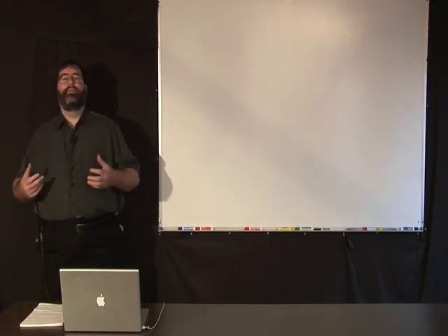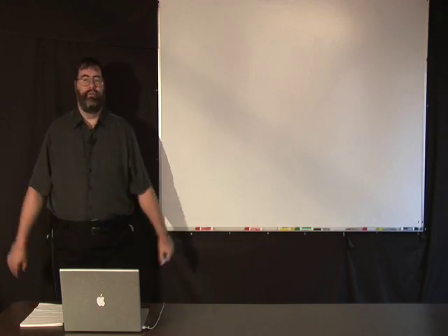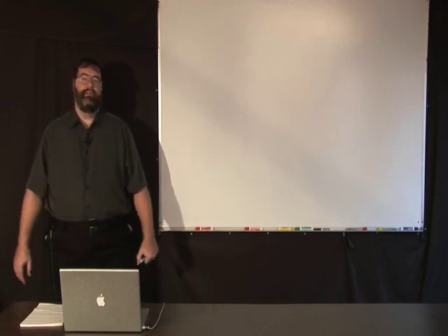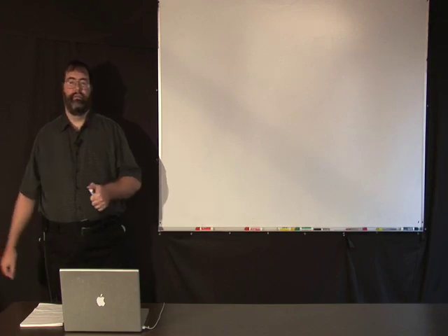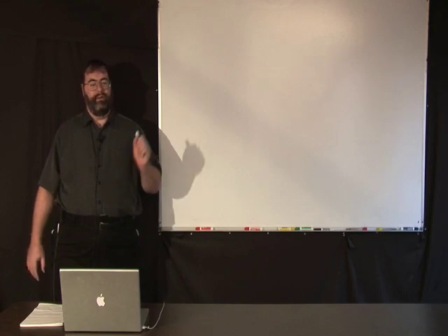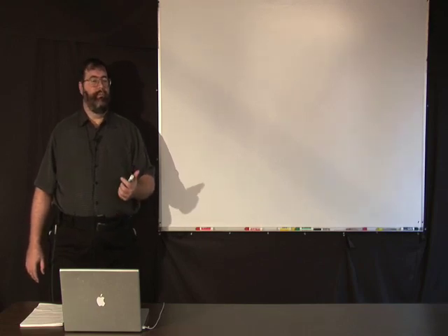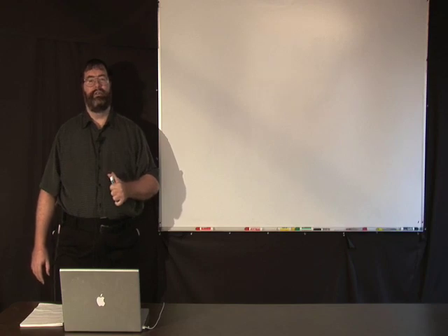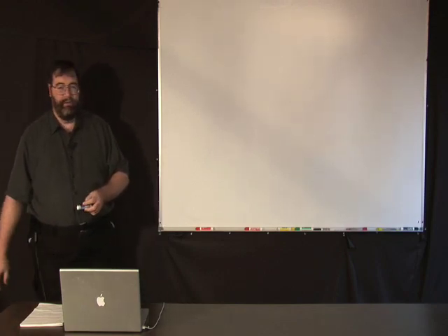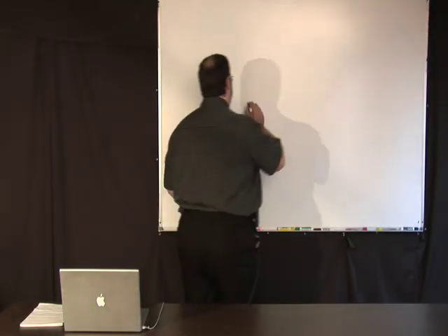Okay, last time we started to talk a little bit about S parameters, and we're doing a short series on that. So the question might be, well, how do you measure those? And the first question is how might you measure reflection? To measure reflection, you've got something going out, something reflected, something coming back. So you need something that can measure the power going in a particular direction. We're going to give an example of a device that can do that. There are other types of devices that do that, but we're going to do something simple.